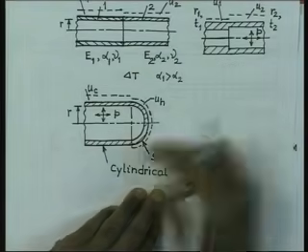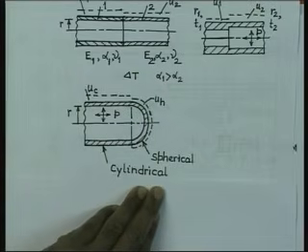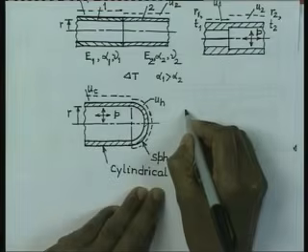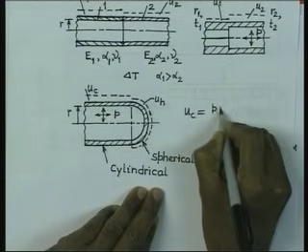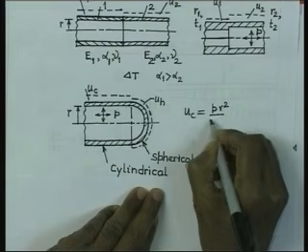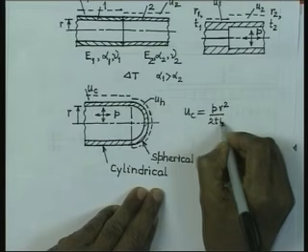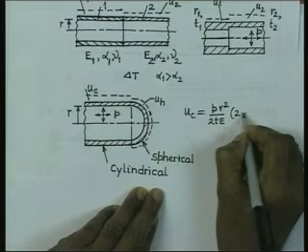since the circumferential strain is given by u by r. u by r is nothing but sigma theta by E minus nu times sigma A by E, and the hoop stress is PR by t and the axial stress is PR by 2t. Therefore, from that you can get UC for the cylindrical portion as nothing but PR square by 2tE into (2 minus nu).